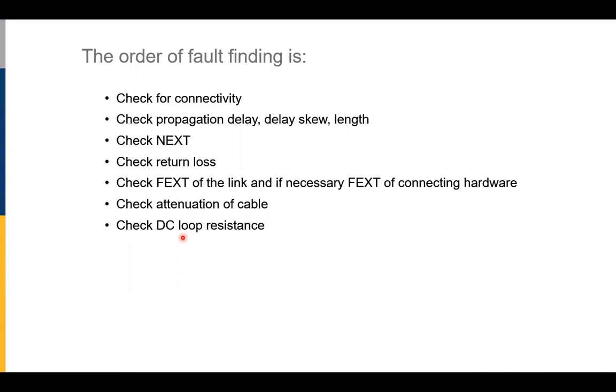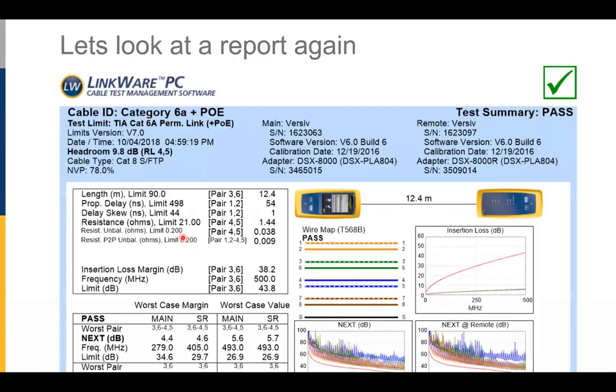There's a cable called copper-coated aluminum, but copper-coated aluminum cannot be category 5E because while aluminum is conductive, it is not as conductive as copper, so you're going to get too high of a resistance. So if you save money by buying fake category 5E cable, many times it'll even say CCA. That's not going to support your Power over Ethernet application, so that loop resistance test is very important.